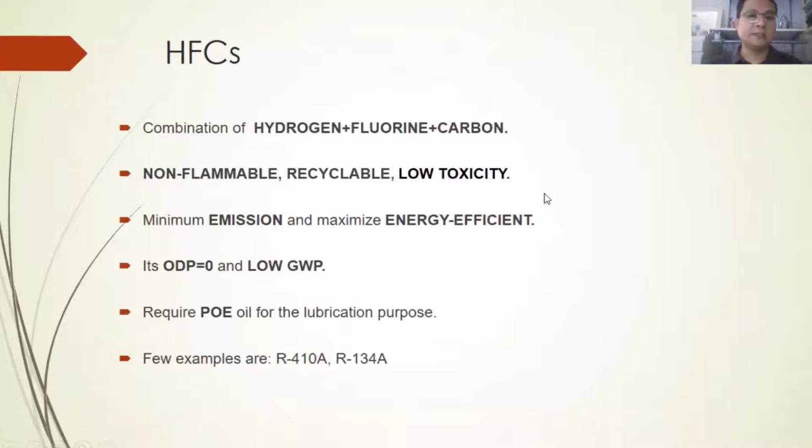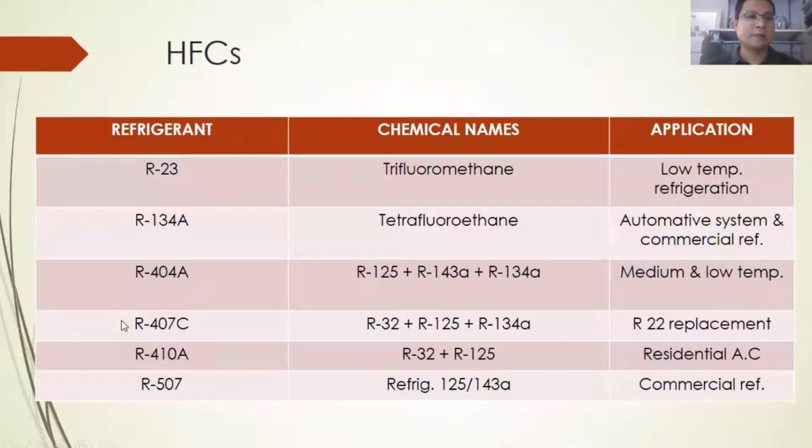Non-flammable, recyclable, low toxicity, minimum emission, ODP also zero, low GWP, and it requires POE oil for lubrication. A few examples, like R410A. This is in the group of HFCs.